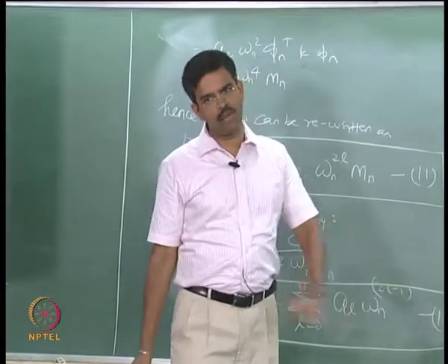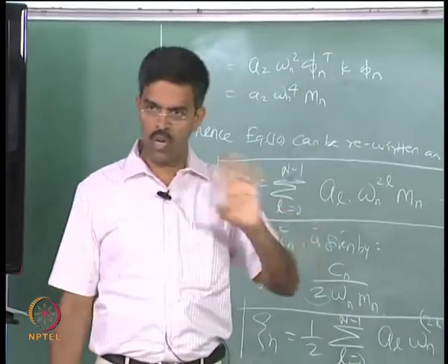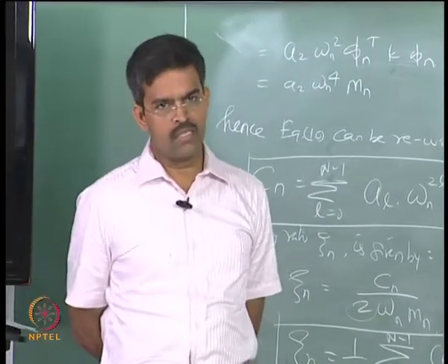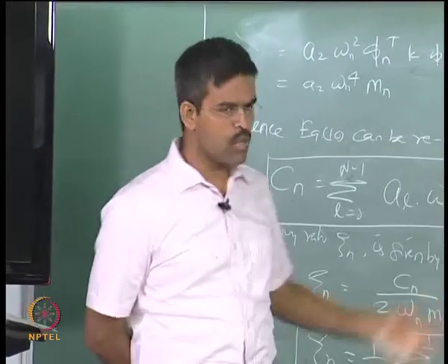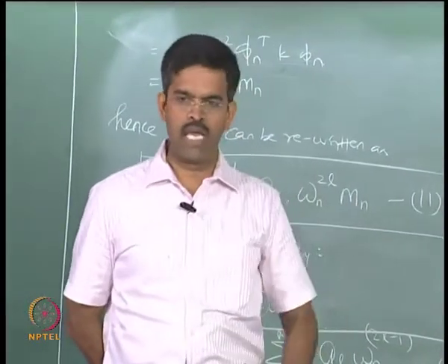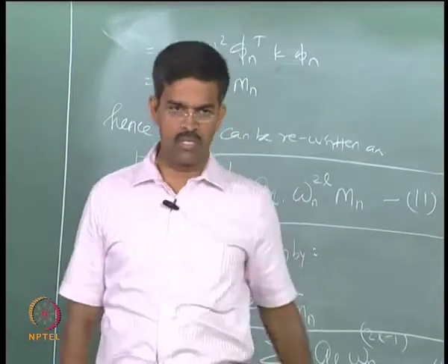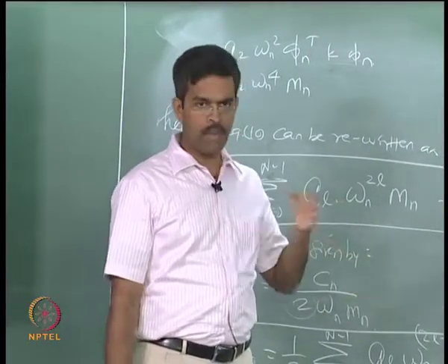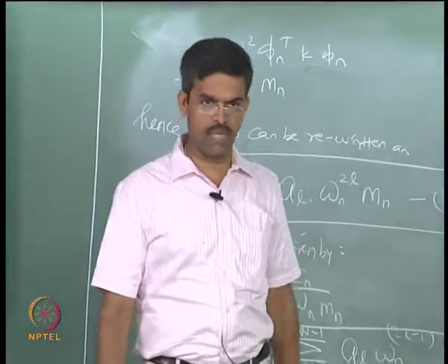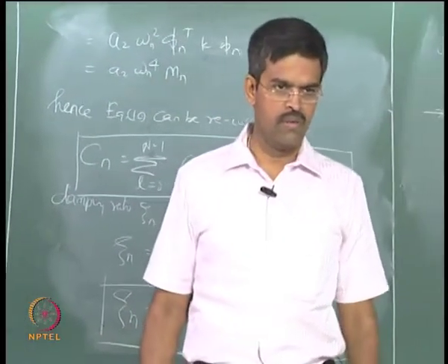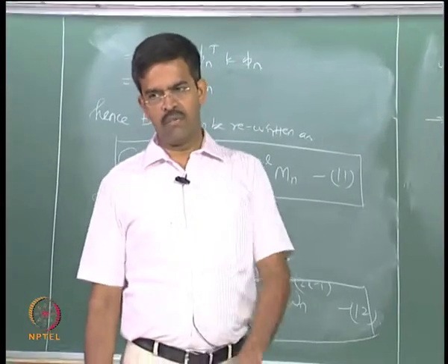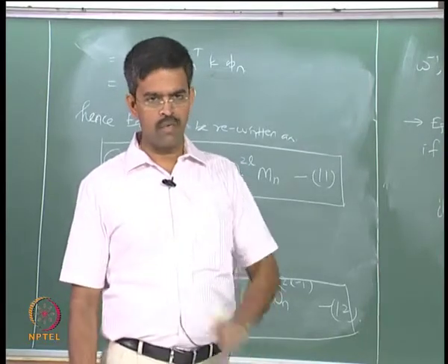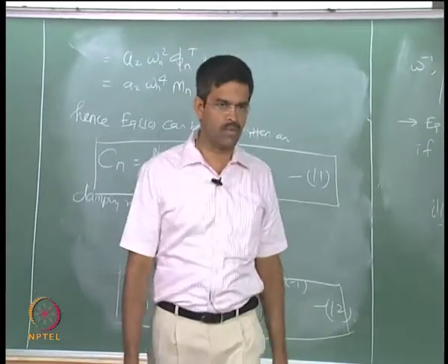So, we are looking at the estimating of damping matrix in this problem, is it not? It can be either mass proportional alone, stiffness proportional alone, but it is not successfully operating in the practical considerations in experiments. So, we are looking for amalgamated models from Rayleigh, from Caughey, and one more method which we will discuss on Monday's class. So, these are some interesting, practically applicable methods for multi-degree freedom systems. There are many more methods, we are not discussing all of them here. By sample I have discussed 3 methods, okay. I have discussed 2 now, I will discuss one more method on Monday's class. So, I will have 3 methods discussed, there are many more methods available, okay.